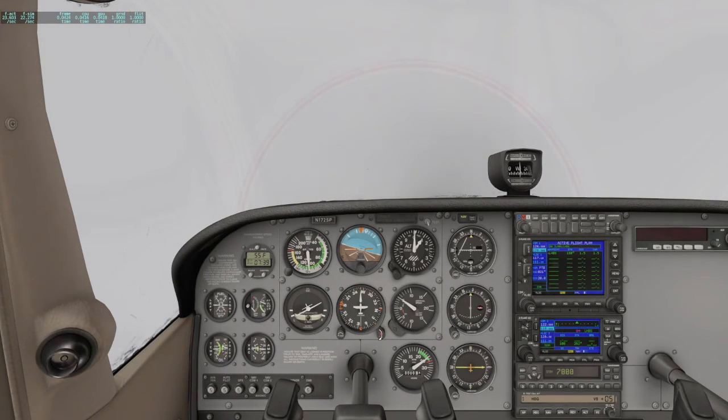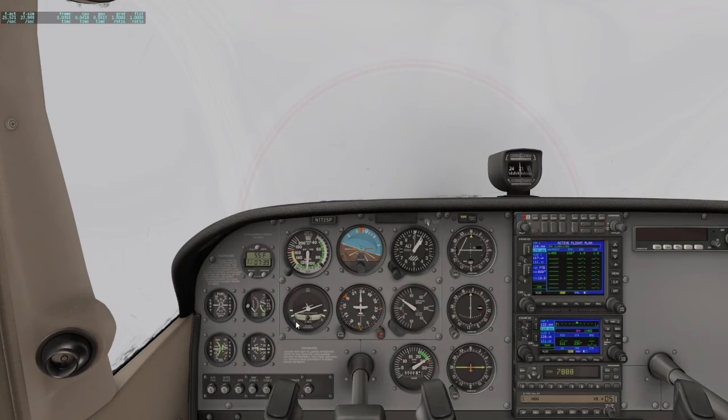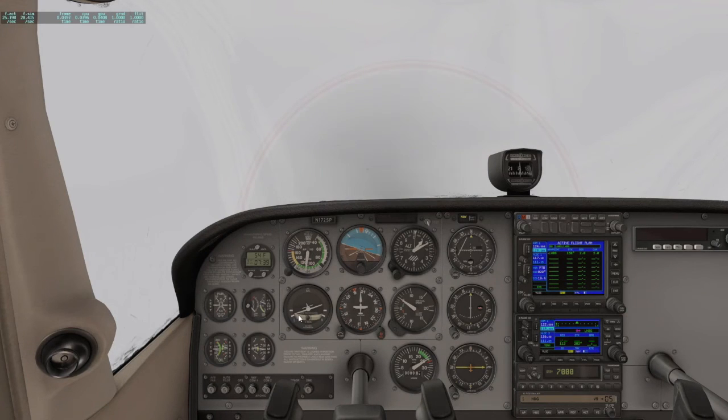As in the video about the autopilot, once you select a specific heading, the aircraft will do a rate 1 turn, as you can see here, where the turn indicator will show you that the wing is aligned with the dot right here, and that means you're doing a rate 1 turn. Okay, so we're climbing. We've got to keep an eye on our altitude indicator.